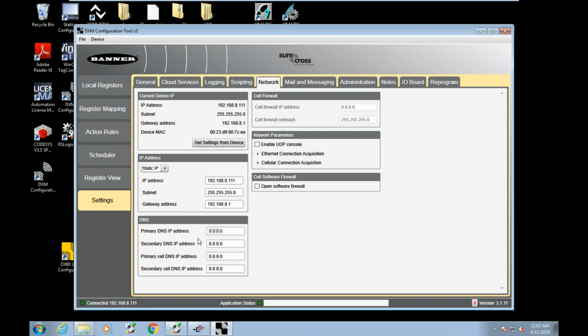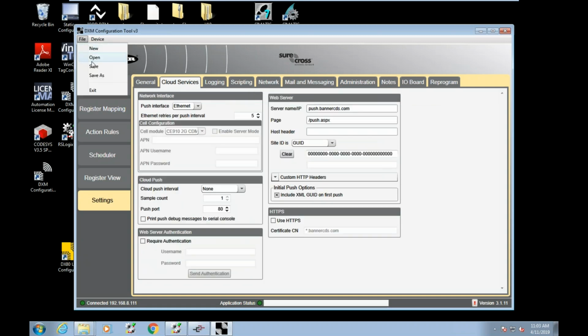It's going to be defaulted back to whatever was set in this IP. Now I really don't need DNS addresses here because of what I'm doing. If I were doing DHCP, the DHCP would assign DNS. If I were doing mail server out of this DXM, that's where I would likely need my DNS. I'll go ahead and enter the Google DNS, but that is not required at this point. So there's my Ethernet settings. I'll go ahead and save here.